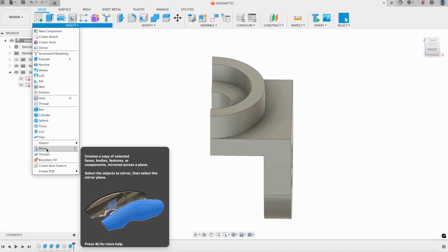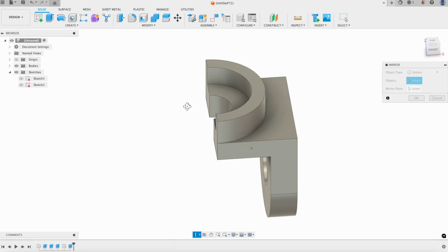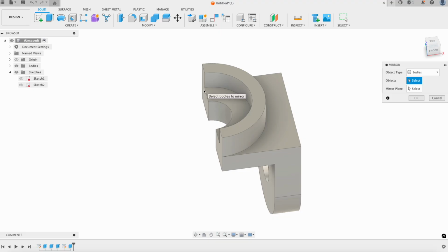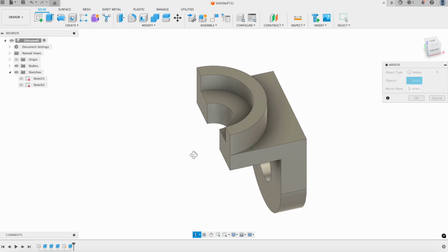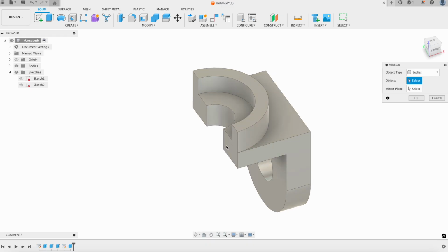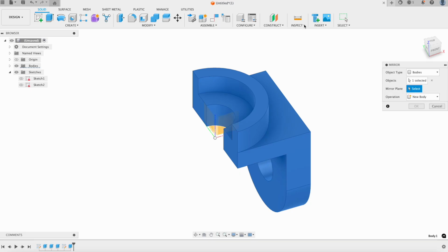We want to imagine that we are taking this and essentially slapping a mirror right on this far side of the object, this spot right here where all of these circles have that line going straight through the middle of it. So in this menu, we can select Objects and then the Mirror Plane. The object that we want to mirror is the thing that we already have created. And then for the mirror plane, we just want to select this face of our object.